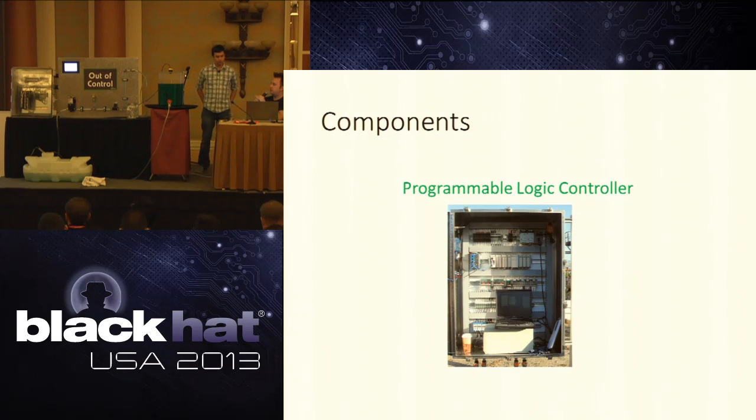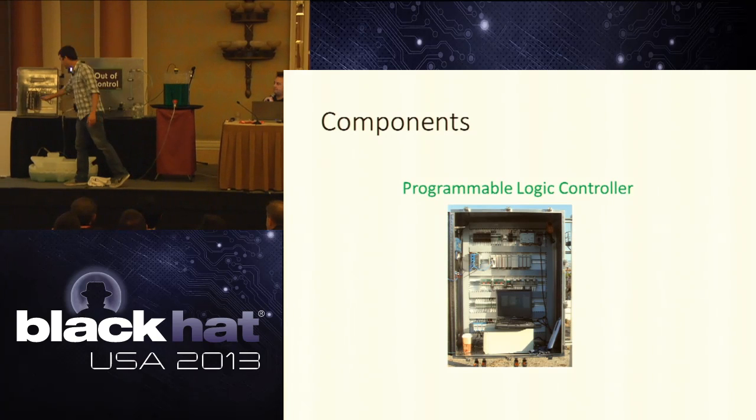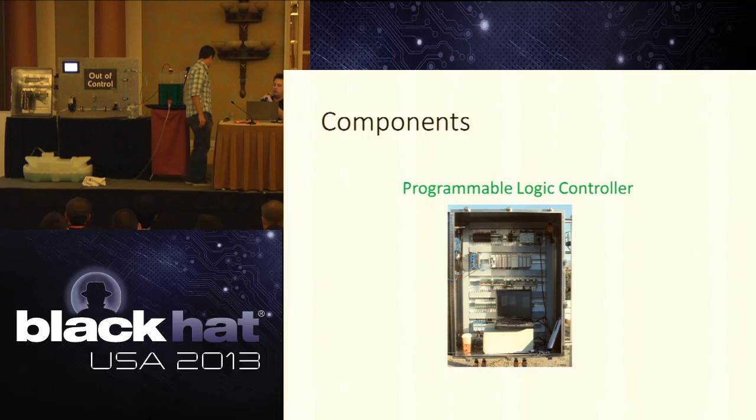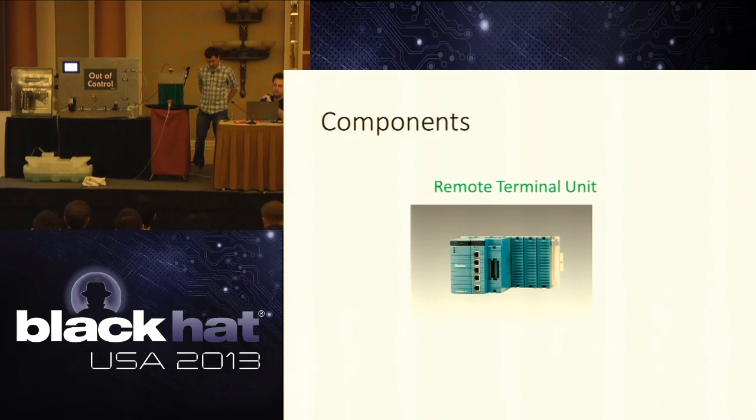The PLC is, do you want to point that out? Yeah, sure. So the PLCs, they're called PLCs, controllers, or RTUs, remote terminal units, but it's this guy right here. He's what actually controls the process. A PLC takes inputs such as a temperature sensor, or in our case a level sensor, and has logic that it acts on those inputs and writes outputs to the system, which controls a pump or a motor or a valve, things like that.